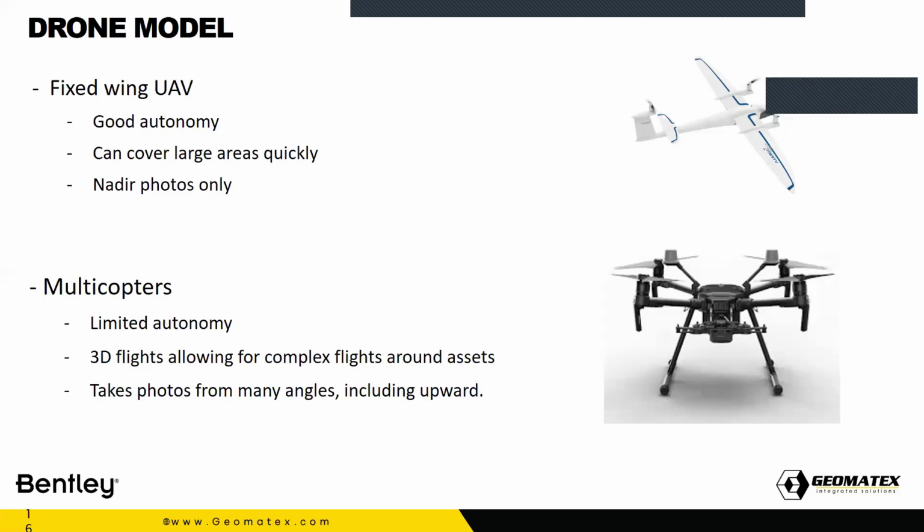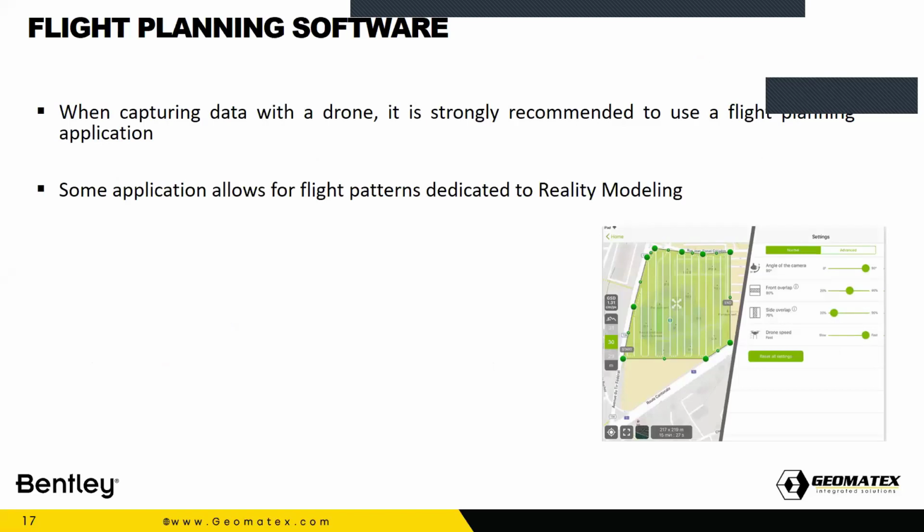So now we had a glance at some technologies we might use. What are the technology updates? How can I do my photogrammetry job or my surveying job with less effort and with high accuracy? For some platforms which don't have any planning software, like the Phantom 4 RTK, you might be able to use any third-party application like Drone Harmony, Drone Deploy, ContextCapture, or maybe DJI Terra. So you will be able to do that in a very, very accurate manner because it's going to be done autonomously.